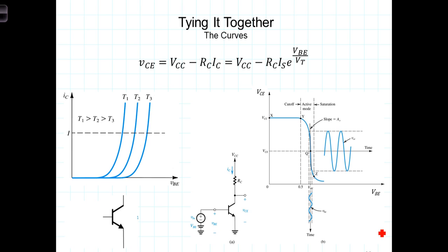So thus far, we have seen that the bipolar junction transistor, like the FETs, has three different terminals. One terminal we've referred to as the base, the other is the collector, the other is the emitter. In this video, we're going to discuss the NPN transistor. The NPN transistor has the arrow on the emitter going away from the transistor. And we define the currents I sub C, I sub B, and I sub E like that.